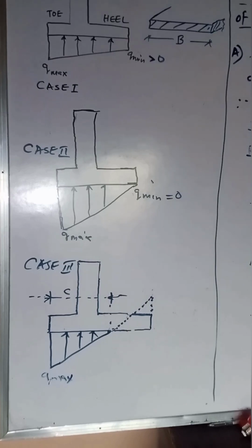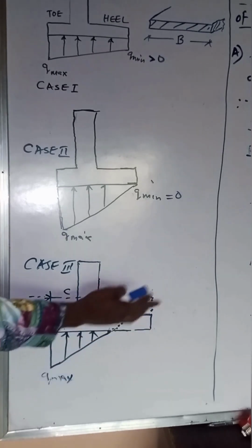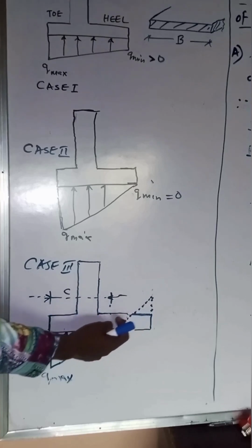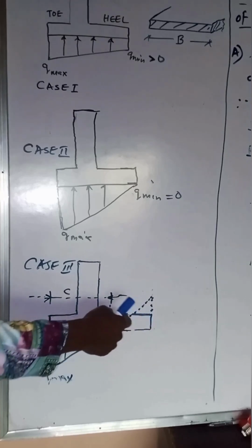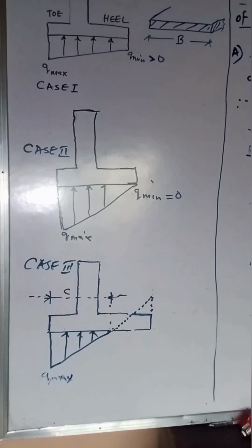Okay, because you can design like this, but it means the whole of this section is wasted, the concrete in this section is wasted, and the steel reinforcing bars running in this direction are all economic waste. But if you choose to go that way, it's okay.